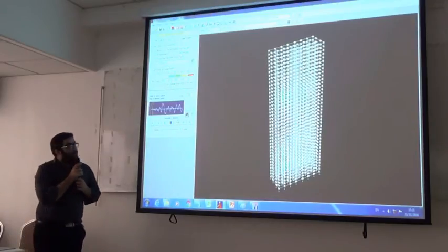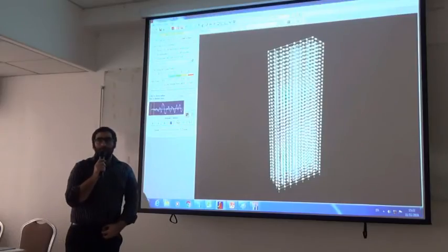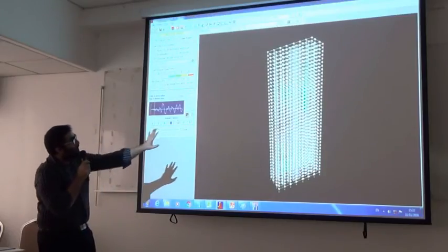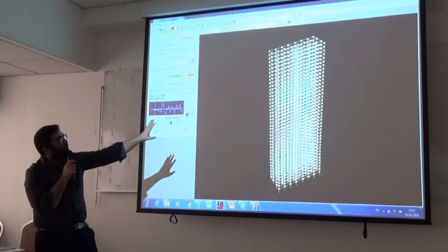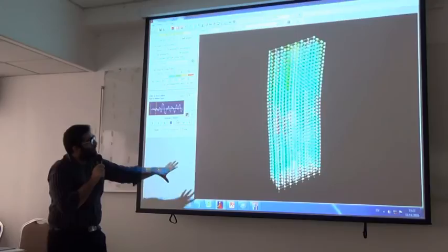Okay, so now the results that you're looking at are the DC ratios for the rotation. As soon as you have a blue color, you can see some blue colors forming somewhere, right? That basically corresponds to the girder yielding. Now the girder moment capacity has already been exceeded.